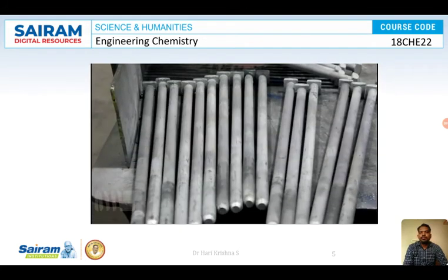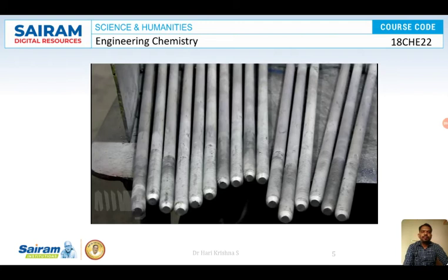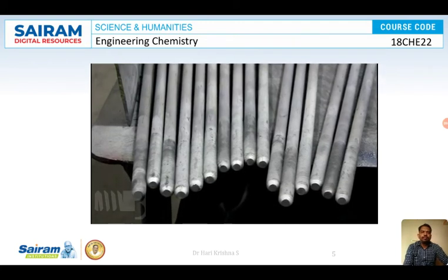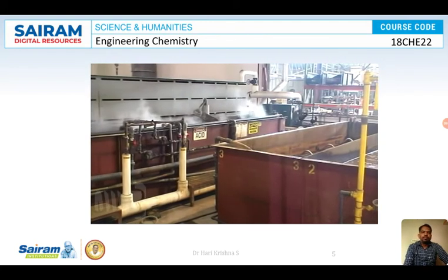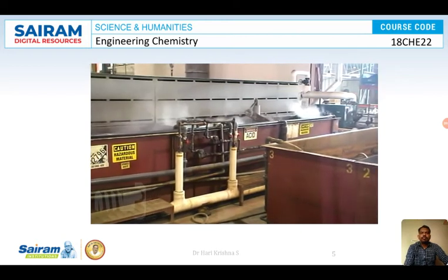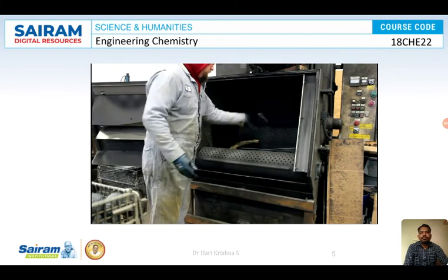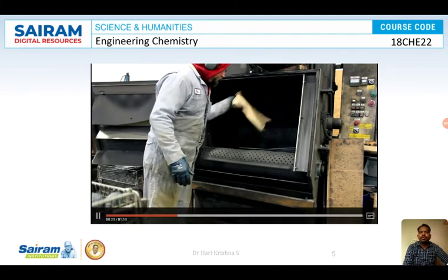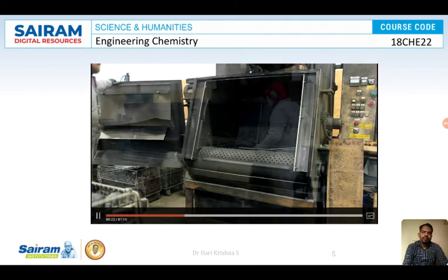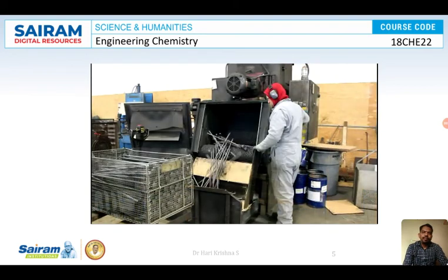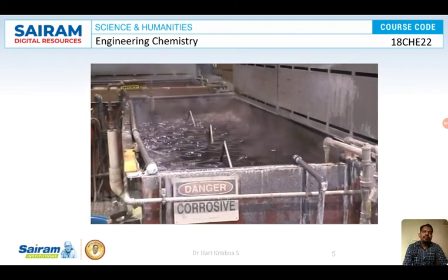The challenge in galvanizing bolts is preventing zinc buildup in the threads, which can prevent nut assembly. Portland Bolt uses a specialized galvanizing process to ensure clean threads. Some bolts are blasted with steel shot to remove the excess forging, heat treat, or mill scale that can prevent the zinc from bonding properly with the steel. This is also done industrially, but for small articles.